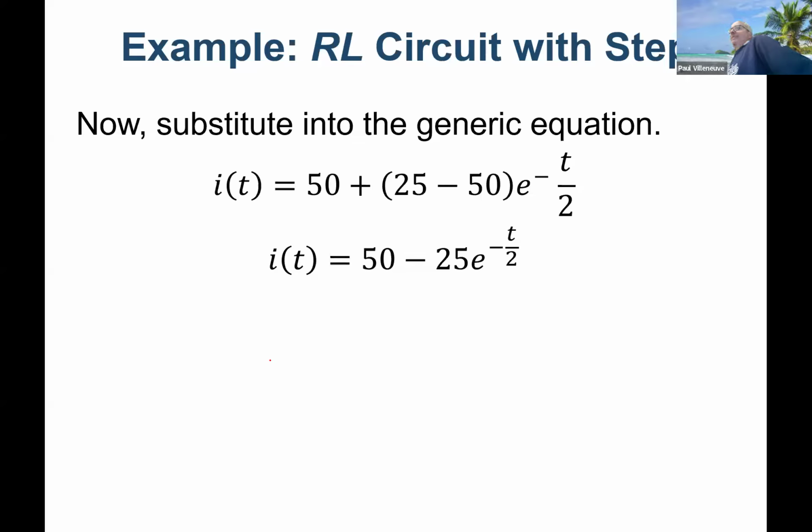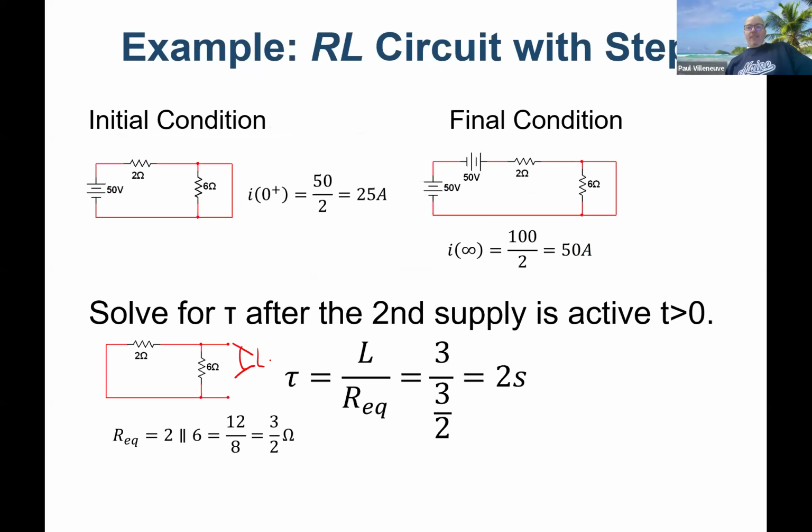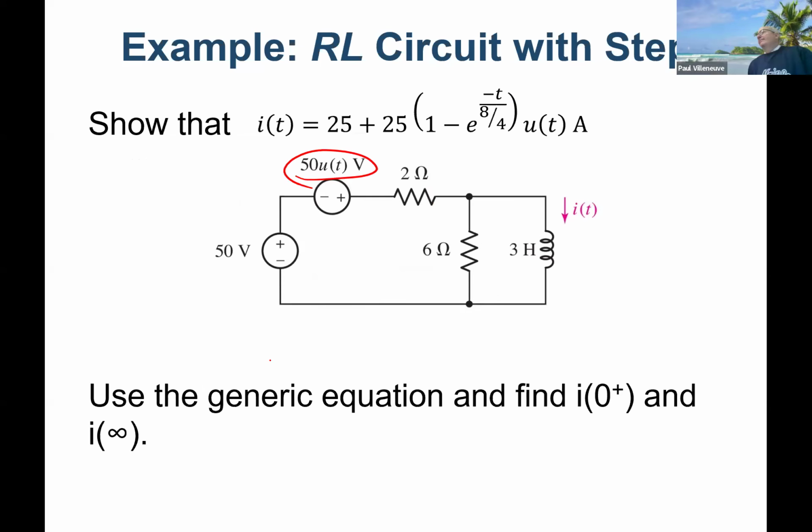Questions on this? That secondary power source of 50 u(t), is that determined by that coefficient 50 after time 0? Yes, so u of t is just 1, and it only exists after time t equals 0. So it's 1 after 0 and 0 before 0. So 50 times 1 is 50. Yep, that's all it is. I'm trying to introduce the concept of the unit step because we need to take advantage of that in our next chapter when we do Laplace. It makes things really important for us.